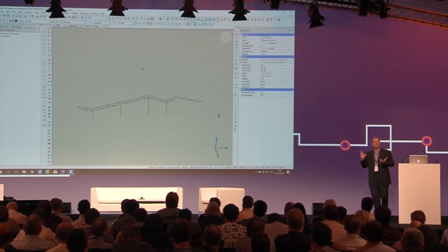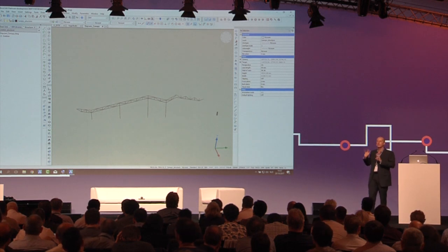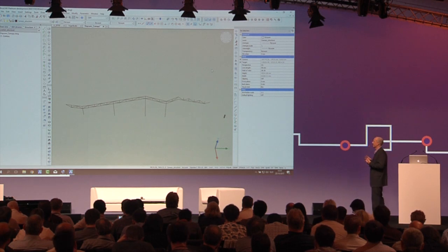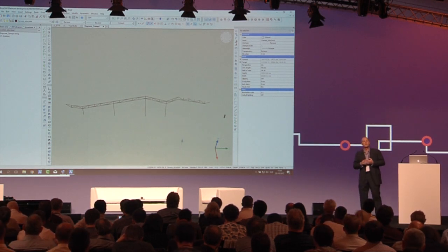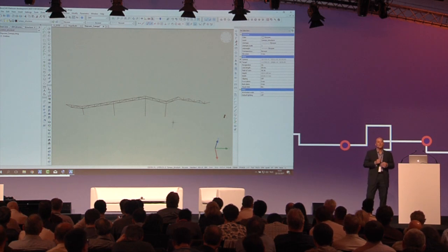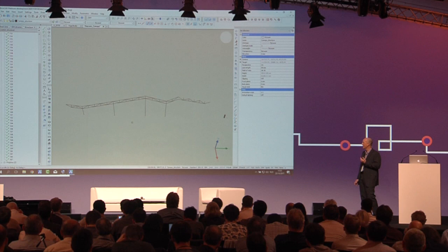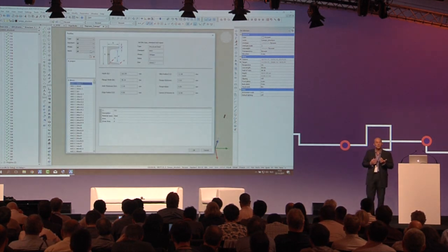And what Jacob's got here is a series of lines that are starting to lay out the initial idea of a truss configuration. So we've got to carry things forward pretty quickly. So what we can do is select 4 of the lines that are representing the columns. We can use a structural tool called BIM Apply Profile. And then we can bring up a dialog box.